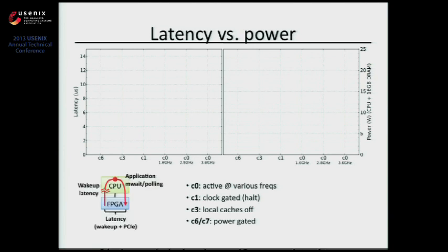And so to measure this, we came up with an experiment where we used our NIC, basically our FPGA card, to generate packets, basically generate writes that go to the application that is polling on a particular memory location, and then simply signaling back to the FPGA to stop the measurement, stop the clock. And so this experiment measures the wake-up latency of our processor and has an overhead of the PCIe round trip.